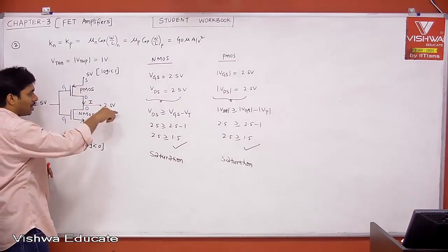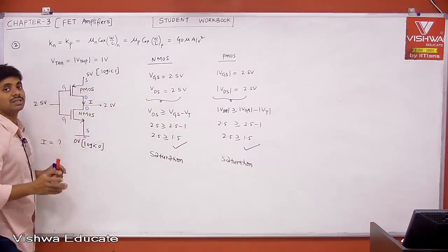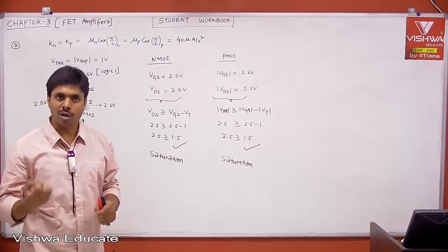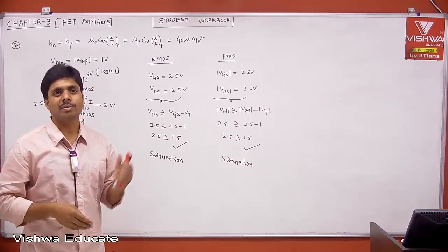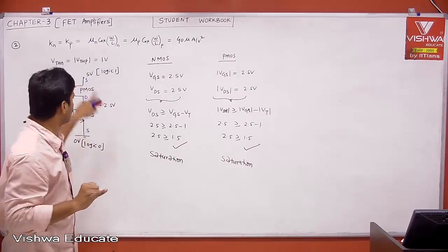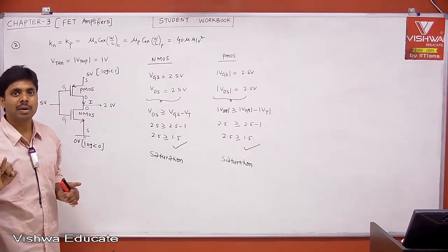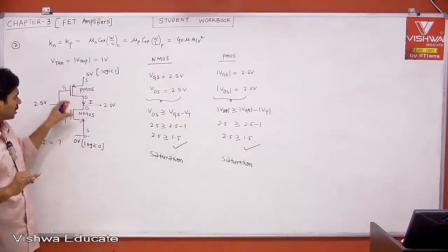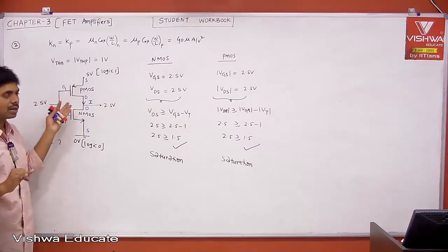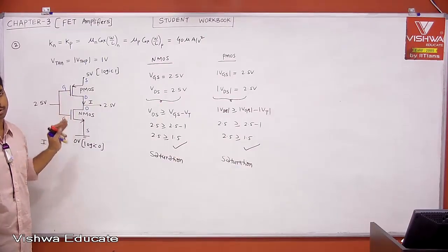See, that current is not flowing into the capacitor, therefore it is not charging the capacitor. This is the current which is going directly to the ground, which is what people call short circuit current, which is unnecessarily one of the components of the power consumption of the CMOS inverter. Actually, there are 3 power components I can say. One is dynamic power to charge the capacitor and then discharge the capacitor. Number 2, static power: when one of these transistors is off, because they are complementary, there is no current. But because of high resistance, as I told you, leakage current will be there. That is static power.